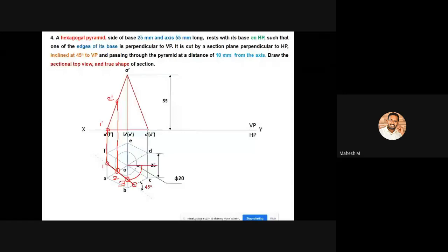Clear? Then what is our next procedure? You have to create a vertical line. So up to which line should you create it? Up to the extreme line. Understood? This line is not the extreme line. It is not a line of slant edge or else extreme line. So you have to create the extreme line too.